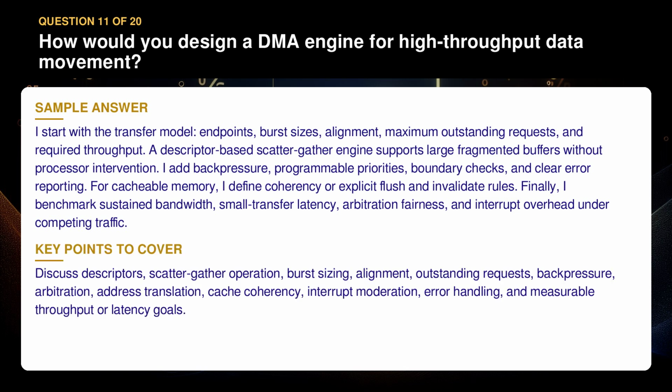Discuss descriptors, scatter-gather operation, burst sizing, alignment, outstanding requests, backpressure, arbitration, address translation, cache coherency, interrupt moderation, error handling, and measurable throughput or latency goals.